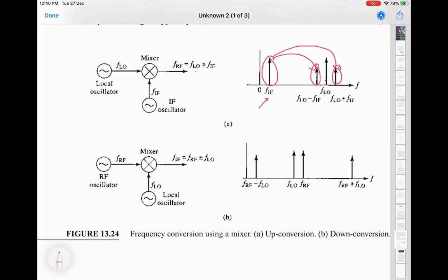It's like 1 plus some small quantity, which tells you how much modulation is happening. But that also comes in here. But effectively, that is what is happening. And then you can think of this output signal, which has this plus and minus IF, as the amplitude modulated signal. So the LO is amplitude modulated by the IF signal, which is the same as saying that they are getting multiplied. Okay. This is just from the AM example.